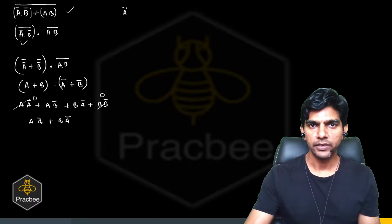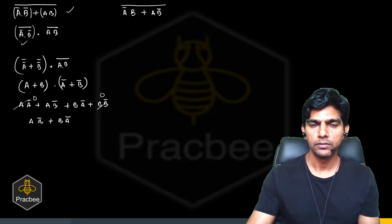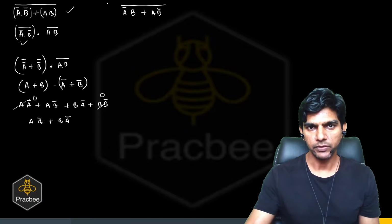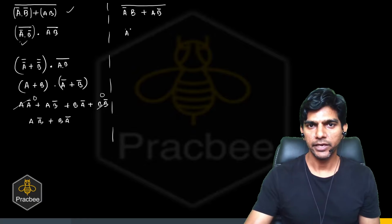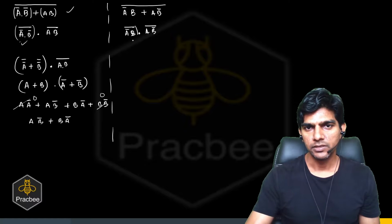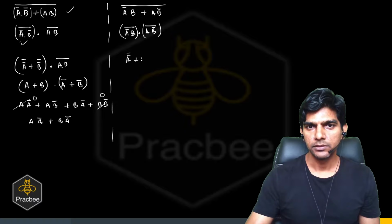Let us say we have (A bar B plus A B bar), and we are taking the whole bar. Let us simplify this. Again, we can apply De Morgan's theorem. So it will be (A bar B) whole bar multiplied with (A B bar) whole bar. Let us apply De Morgan's for these two terms. So it will be (A double bar plus B bar) and (A bar plus B double bar).